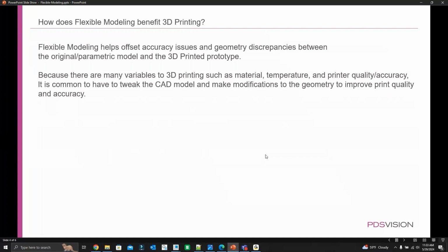In Creo 7, they introduced multi-bodies. What's nice about that is you can create bodies in your model tree of the extrusions that you make and different features, and you can actually create a prototype of an assembly in one part file, and the parts would be the bodies in that one part file. Then you could convert the bodies to parts. And when you convert a body to a part, that part file has an external copy geometry feature. So there's a link there between the parametric multi-body part and the part created from that body,